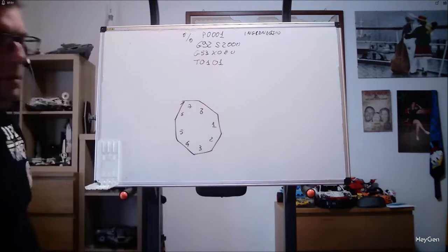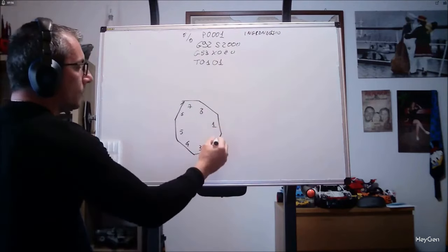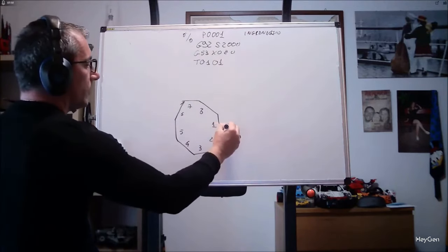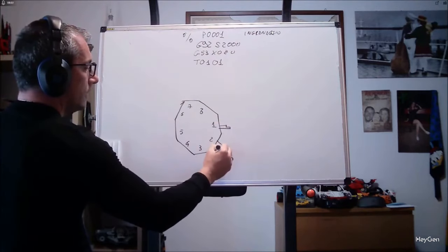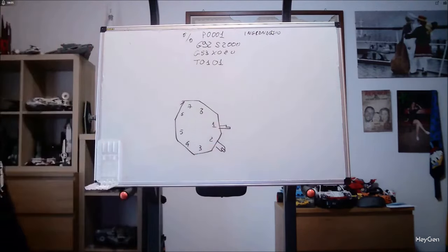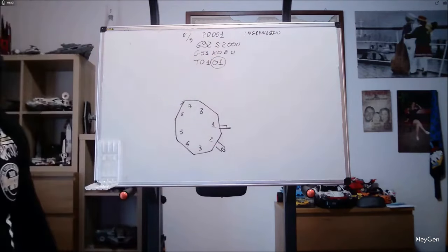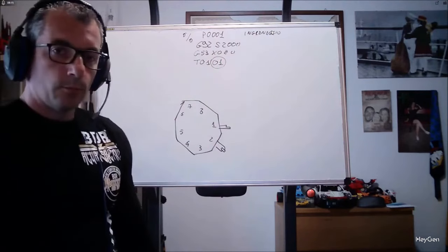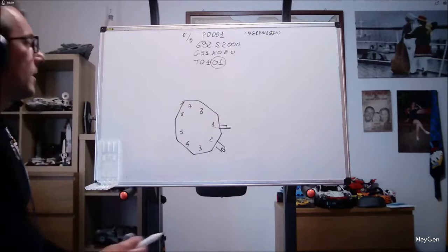You will mount a series of tools on these positions. So if you need a tool for grooving, rather than a tool for external turning, you will call T1 or T2, 01 or 02, meaning the offset, for this little number here. We will talk more about the offset later, just so you know. Because at the beginning of the program, you must call a turret.